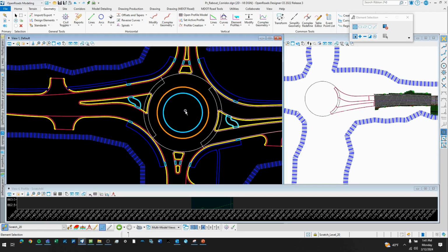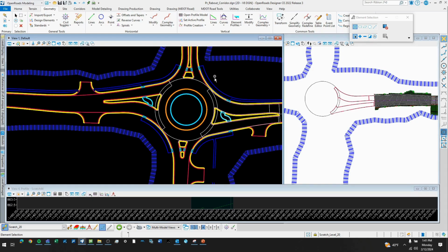There are a lot of different ways you can go about this. For us, we had some issues. We had some really tight right of way and a potential owner who would maybe be difficult in terms of selling. So we wanted to limit right of way in this northeast quadrant. In our head, we wanted to keep this area as close to existing ground as possible to keep those slope stake lines pretty tight along this curve.